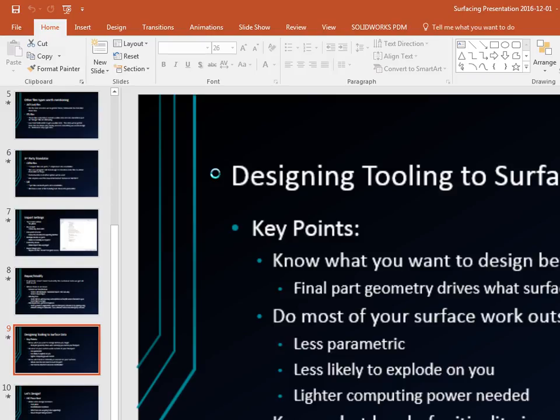Put it in an assembly, and then just do a save as to this part, edit the base sketch to shift it over to be my new nest, do a save as to that, edit the base sketch, shift it over to be my new part. So basically getting one nest done and then utilizing the geometry and the work that I've done